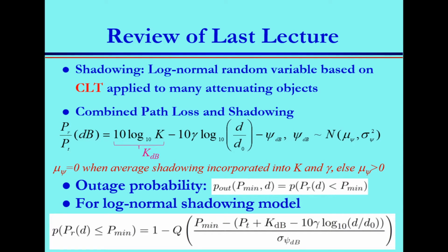The distribution is usually Gaussian, and that's why we model shadowing in most of the cases as log normal. Normal means normal Gaussian distribution, and log, it's like a mathematical operation that can simplify your calculation or simplifies your modeling.